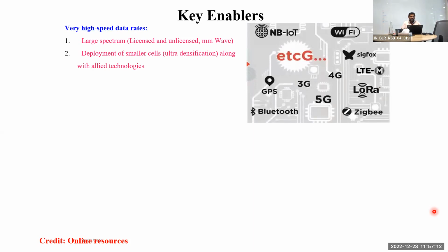For example, as you are doing for 2G, for 900 megahertz you can put a tower up to, for example, on highways, I think 15 kilometers, sometimes 20 kilometers, even beyond that also. But in a city you can have a tower every, for example, 1 kilometer or so, and so on.